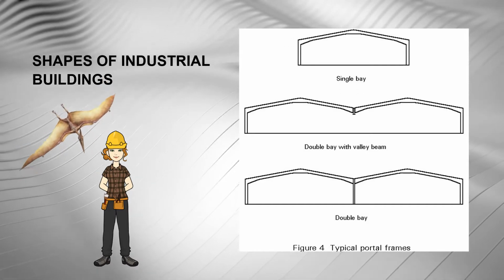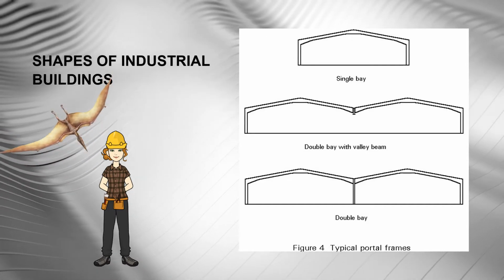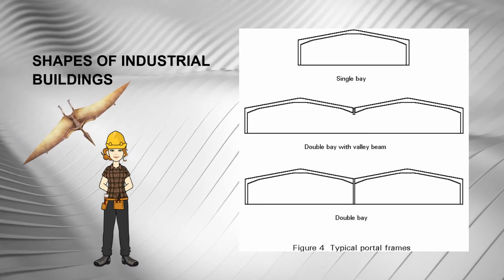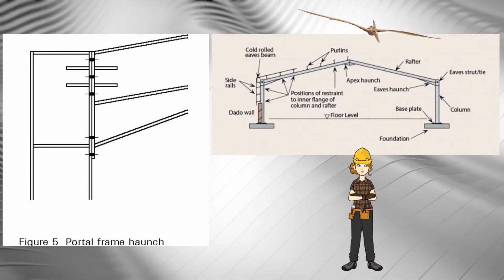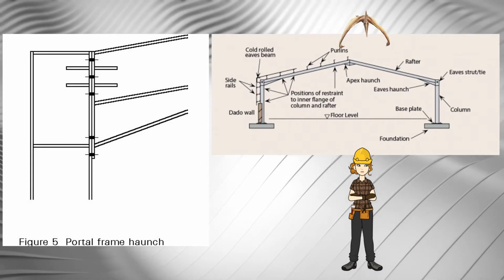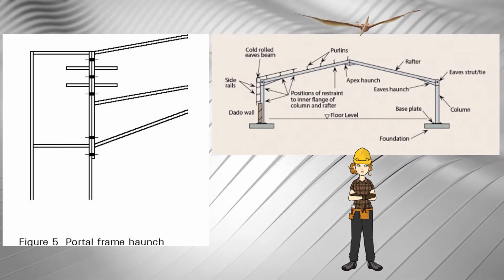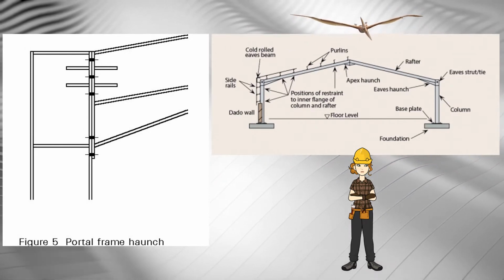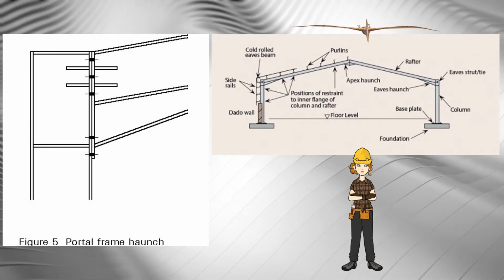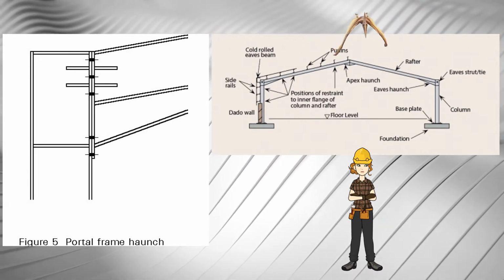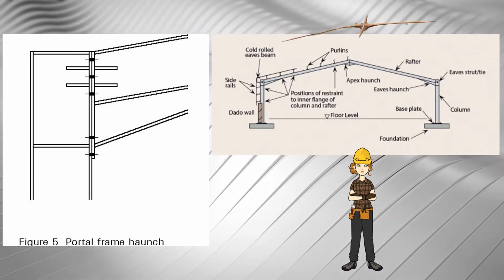Hot rolled I-section, welded or cold formed sections are usually used for the members. During recent years, an increasing use of welded sections has occurred. This increase is the result of progress achieved in making welding automatic and the ability to adapt the cross-section to the internal forces.